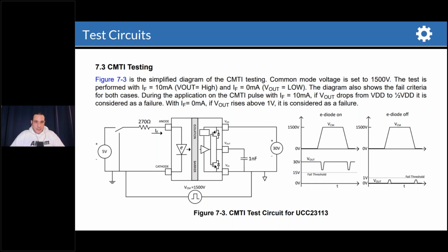The other thing that you'll see commonly is a test circuit. So this is not the same as an application example. This is just a circuit for testing whether or not the component is performing one of its core functions. This is, again, an example for the UCC component that I presented earlier. And you can see here that they're showing some expected data as well as the test circuit that you would wire up and the procedure for running this test circuit.